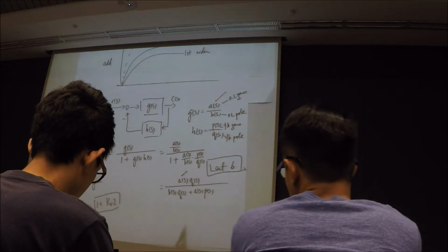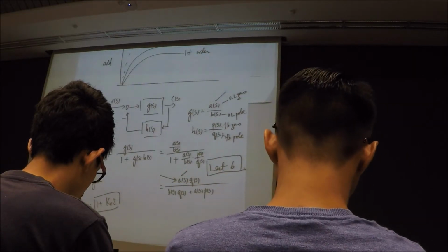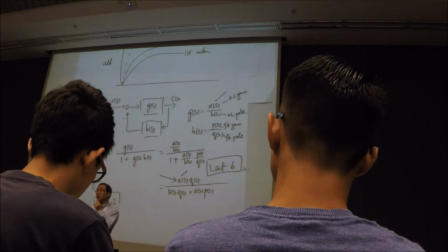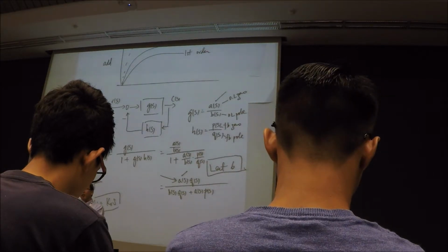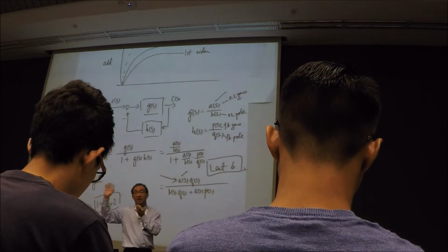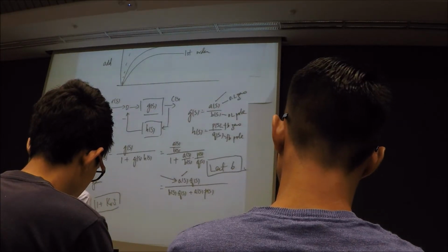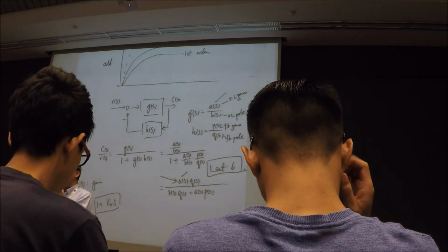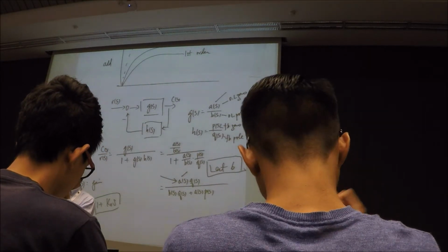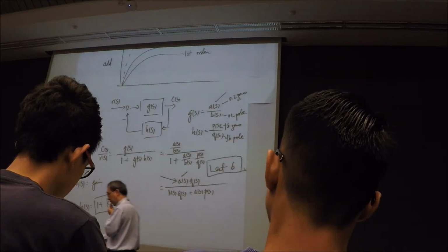As a result, it does not violate what your lecture material mentioned: your closed loop zero is just going to be equal to A(s). But you have to bear in mind that what you have learned assumes your feedback block is a gain. When your feedback block H(s) is not a pure gain and has a pole, that pole ends up in your closed loop zeros. So you have to bear that in mind.